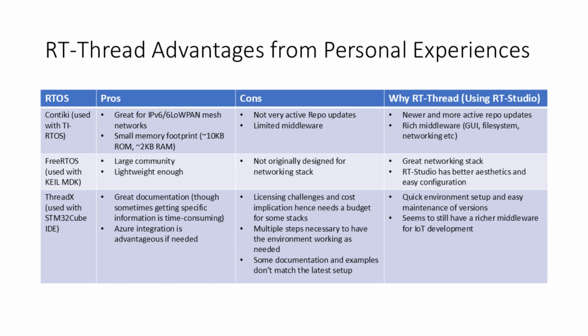Contiki we found to be very good with very good mesh network capabilities and a very small footprint in terms of the memory usage. However, one of the major problems was that updates were very infrequent, and it also had a very limited middleware. This was a big problem for us because it meant that it was not very maintainable and not really up to date.